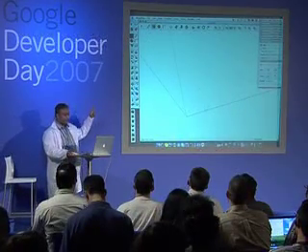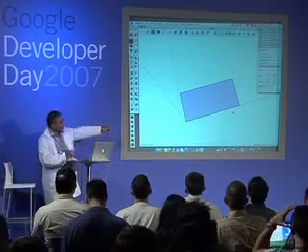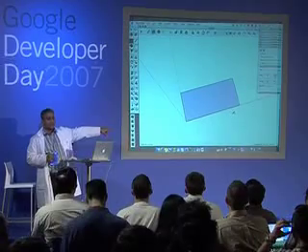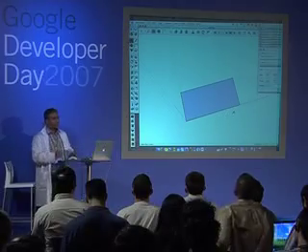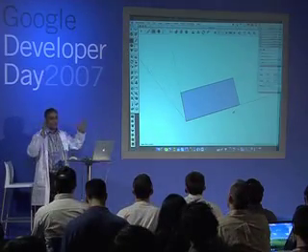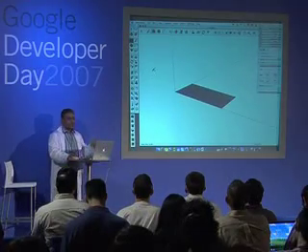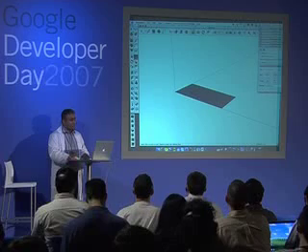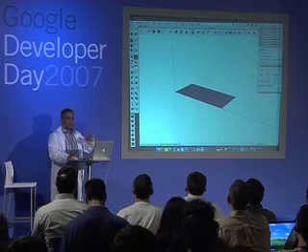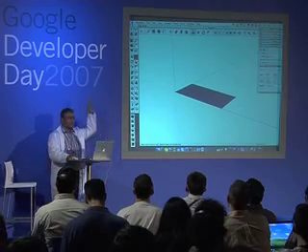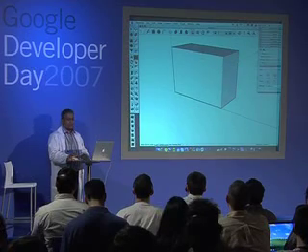I'm going to choose a rectangle, and I will draw one rectangle. At the bottom, it tells me what size that rectangle is. I'm not worried about working 1-to-1 scale. I just want to draw some. I can always go back afterwards and make everything real size. Okay. When I have this shape, if I wanted to make 3D, I just choose the push-pull tool. This is the most important tool in SketchUp because it works like you think. I am thinking now, this is flat, I want it to be this high. So here is push-pull, I want it to be this high.